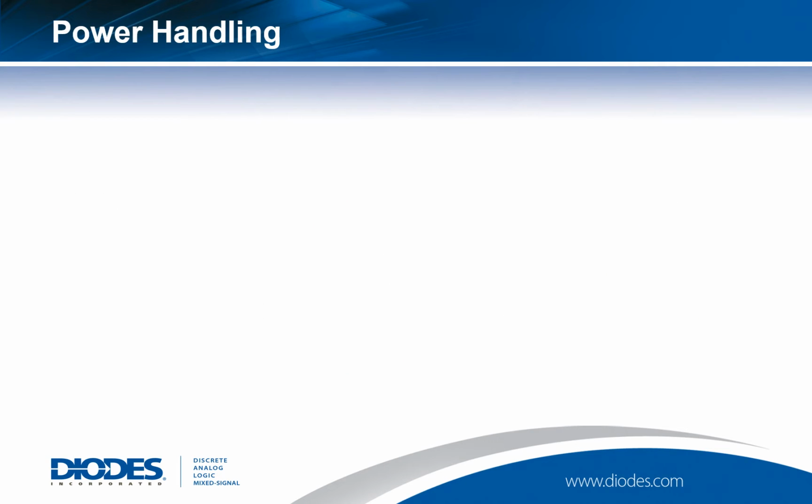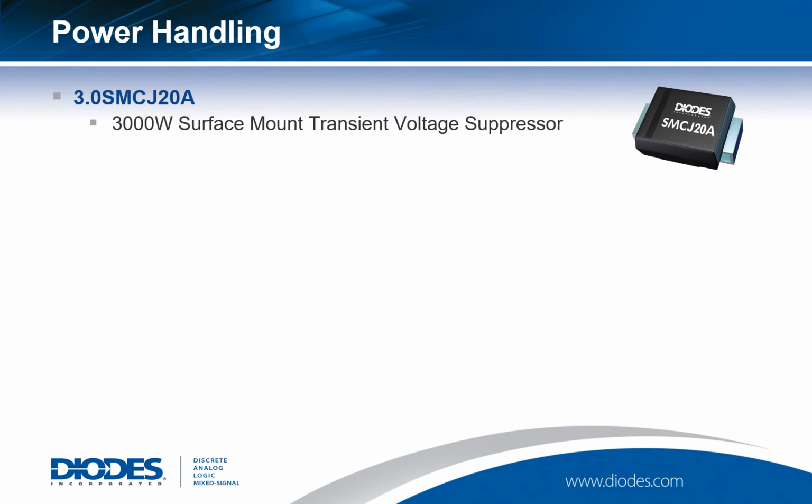Let's talk about power handling. If we start with a fairly common, well-known device that many of you will have come across, a 3.0 SMCJ20A. And if we read the datasheet, the headline of the datasheet describes it as a 3000 watt surface mount transient voltage suppressor.